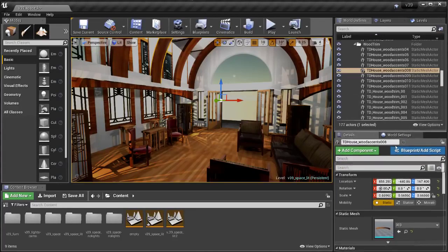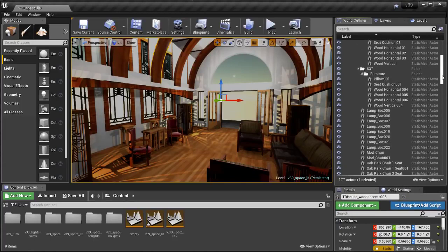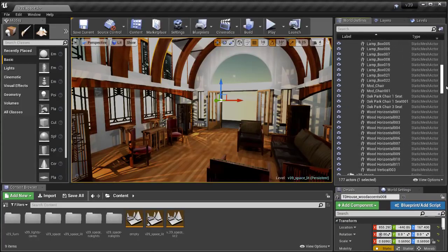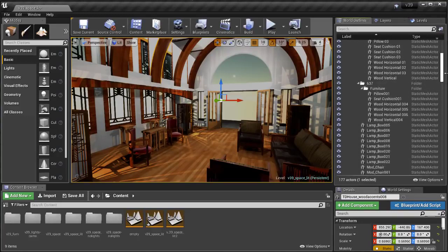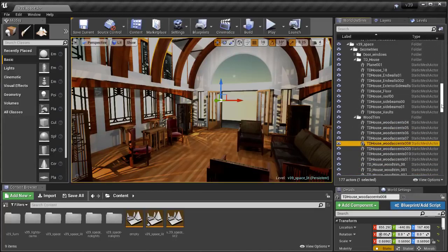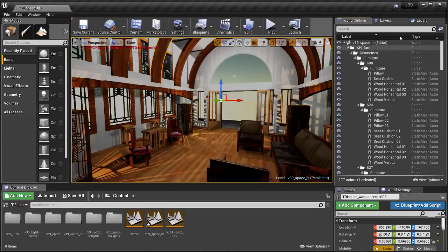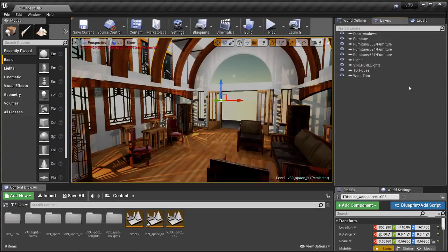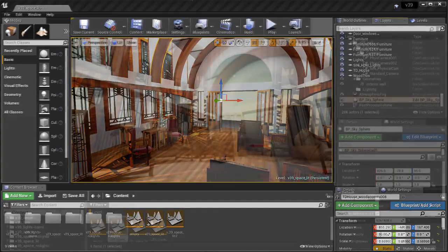And again, just double checking to make sure that all of the scene hierarchy is still in place. Everything that we had set up in 3ds Max is there. For some of the instances, explicit objects are made, so you may see some things with different object names than what we had in 3ds Max. Again, this is part of the process. Layers in 3ds Max are also respected. You can also see that it generated a number of new layers based on some of the instancing that we had going on in 3ds Max. Datasmith does support instancing and XREF objects as well. So those are brought in and organized specifically. So at this point, we're ready to do a light bake and see how our lighting can turn out.